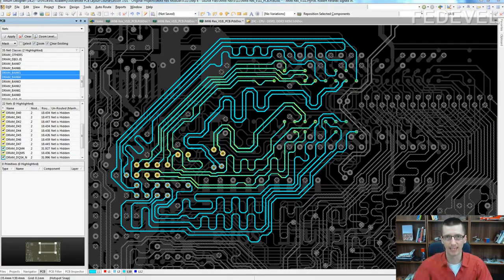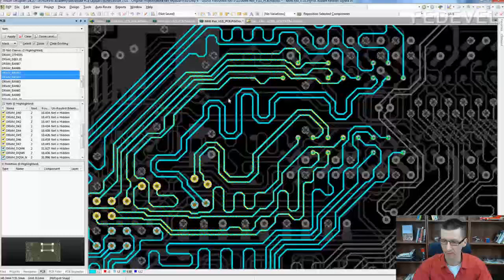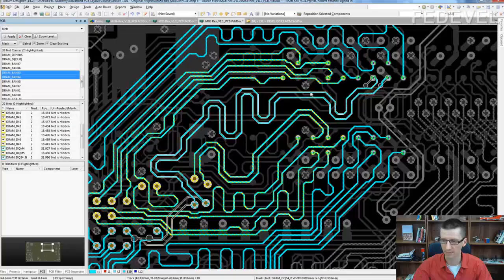One of the important high-speed design rules tells us that we need to keep a big distance, a big gap, from signals such as clocks or differential pairs. You can see it here. See? Here are DQS signals, differential pair signals. Here are data signals, and there is a big gap between them. See? These data signals are routed much closer to each other. Here is also a big gap between this differential pair, DQS, and this data signal here. And we need to keep a big gap between the differential pairs, or as big as we can.